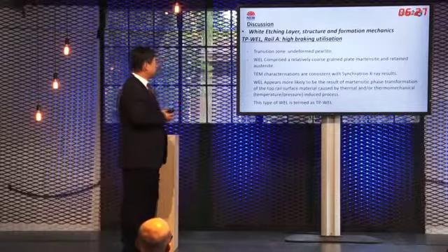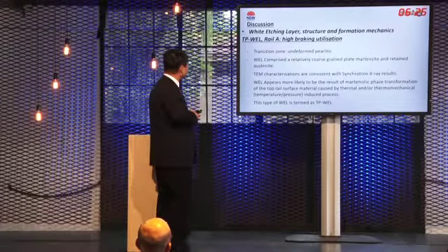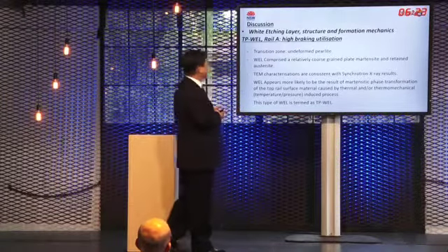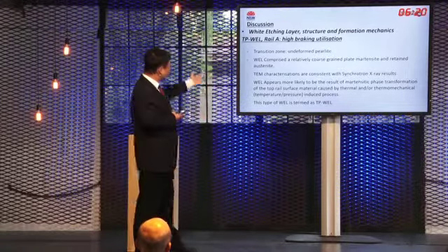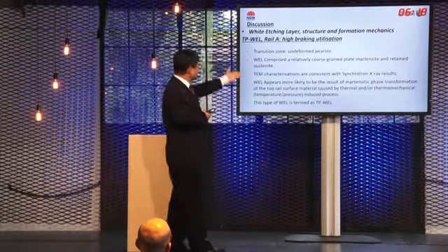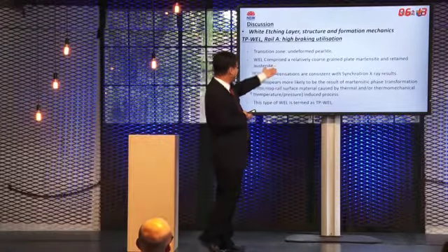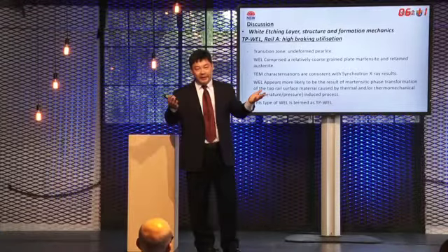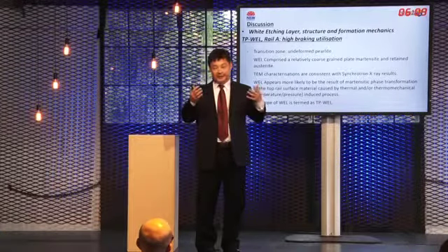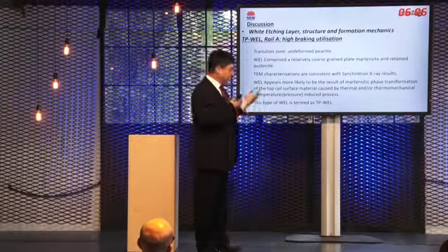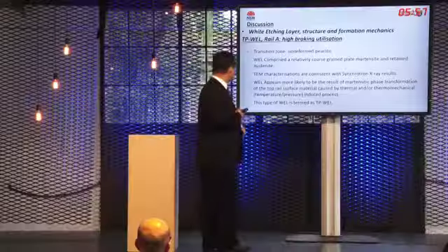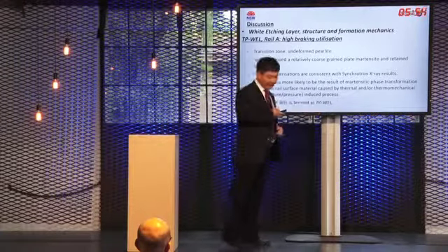A little bit of short summary before I move forward. Region A, for the high braking region, we found undeformed pearlite structure consisting of martensite and retained austenite. It truly indicates it's caused by thermal transformation. Thermal transformation is not only influenced by temperature, but also by pressure. Pressure reduces the requirement for the phase transformation. So we call this the TP white etching layer.